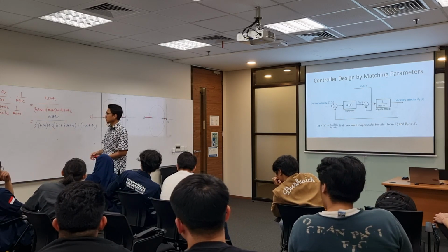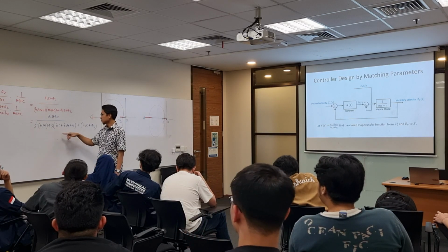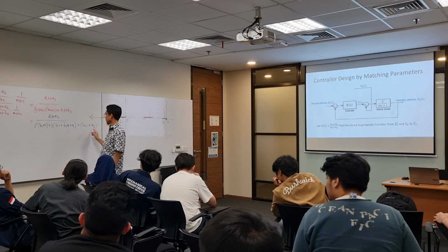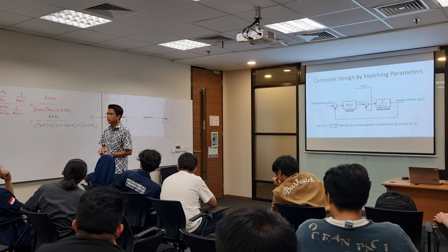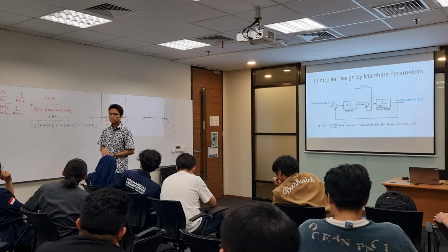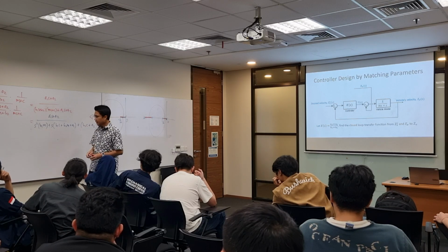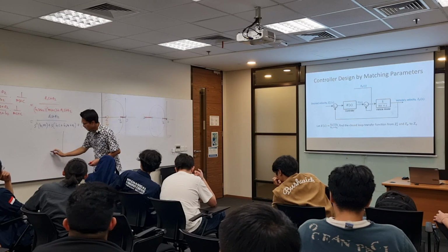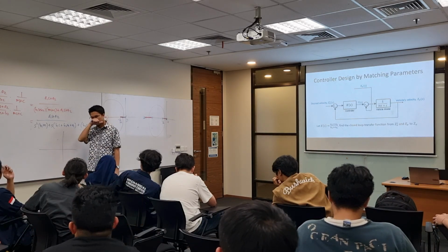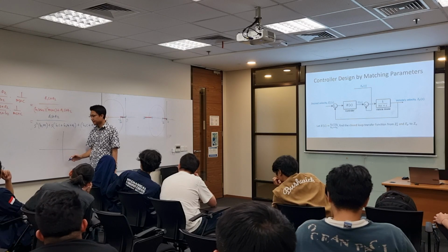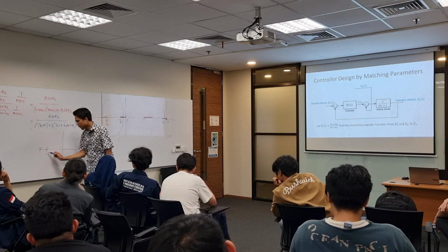Okay. So how do we adjust the values of B1, B2, A1, and A2 here? In this case, what do you do? If you want to adjust this, the first thing you do is set your desired pole locations. Let's say you want your closed loop poles to be at -5 and then -10.